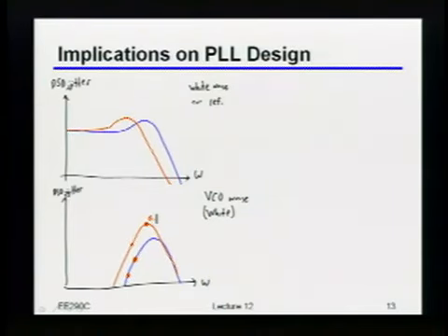But wouldn't it still be at low frequency, right? Well, it depends on where that 1 over F cubed corner is relative to your loop bandwidth, right? So if I had a super low loop bandwidth, then you would indeed see that 1 over F cubed corner due to the VCO, right? If I have a high loop bandwidth relative to that corner, then you won't really see it, because you'll just be killing it by the gain of the loop. Does that make sense, or?